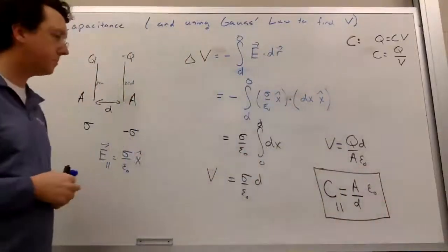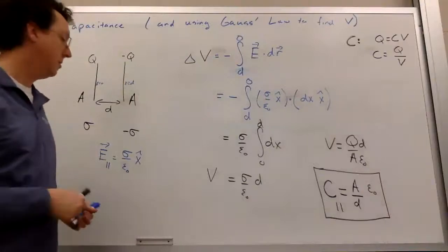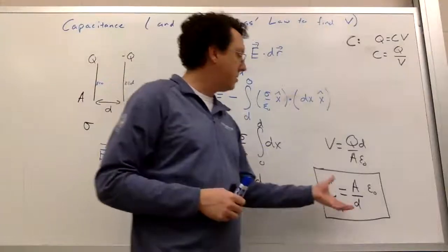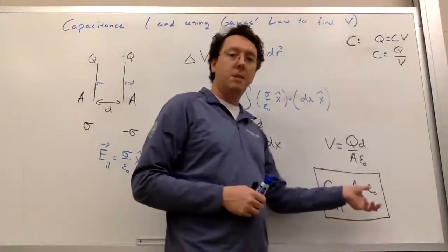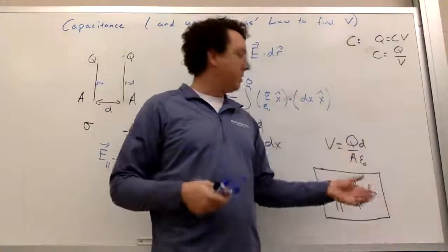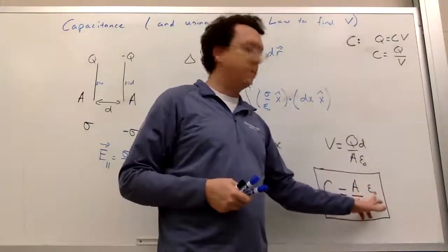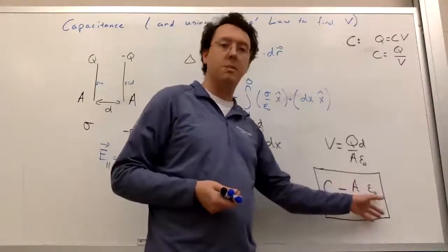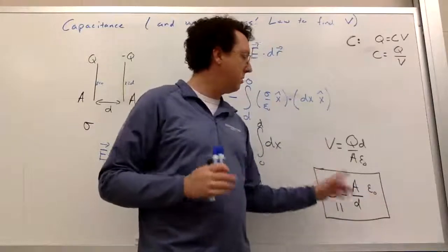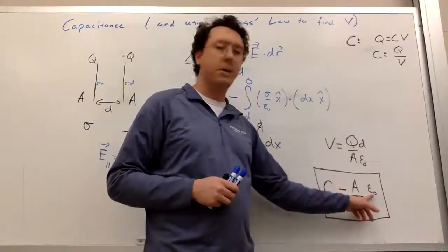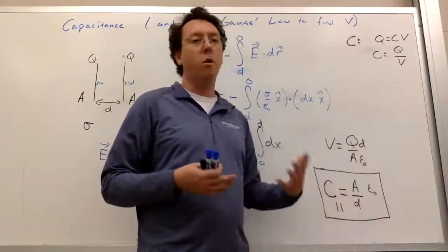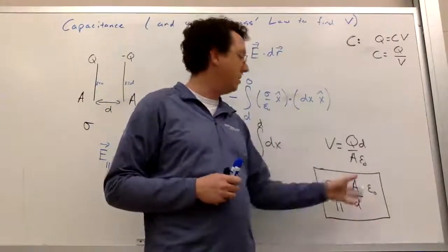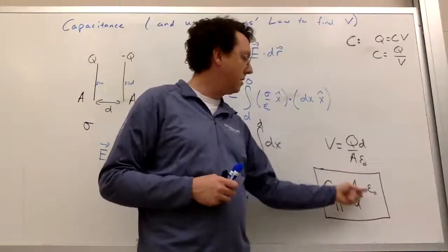Okay. Some comments. Capacitance, when you work it out, is always geometry times epsilon naught. Or when we get to dielectric materials in just a bit, you might replace epsilon naught with the appropriate parameter for a different material. But it's always geometry times that. And dimensionally, it's a length times epsilon naught. But the geometry part typically won't just be a length. It can involve logarithms and other things as well. So it can be more complicated, but unit-wise, it has units of length times epsilon naught.